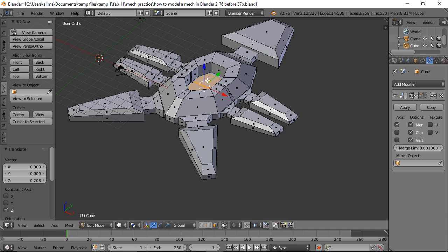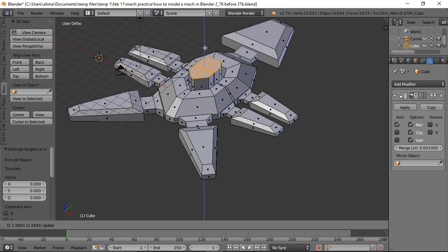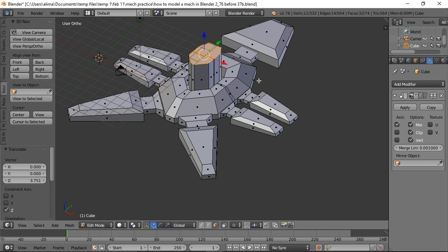Now you just scaled it down just to get some space between the edge of this wall and the geometry you currently have selected. So now you're going to press E to extrude, left click to lock in. When you press that E to extrude, you just created new geometry. So now you're just going to pull up like this. Then I'm going to press A to deselect.